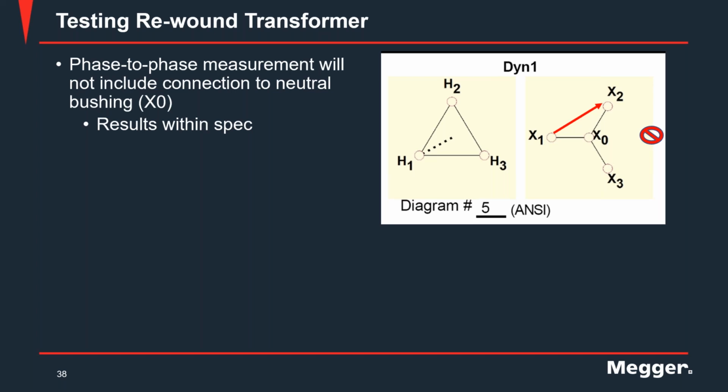Okay, thank you for that question. The answer is that the flux is used, but for the purposes of winding resistance measurement, you are more interested in making sure that you're saturating the core than understanding the saturation characteristics of the core with DC, because the transformer is, after all, an AC machine. The flux that is used during the normal operation of the transformer is analyzed using the excitation current test.